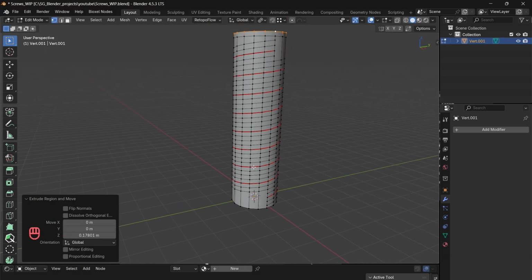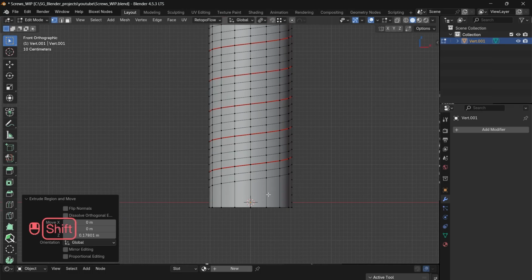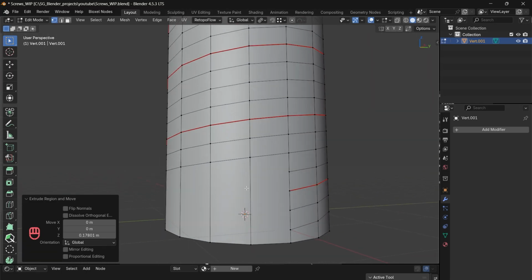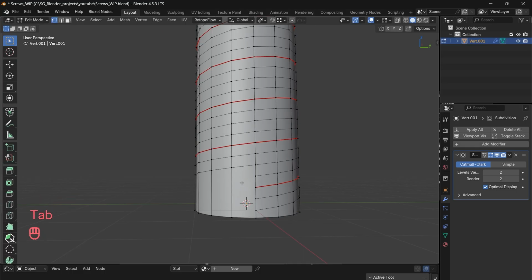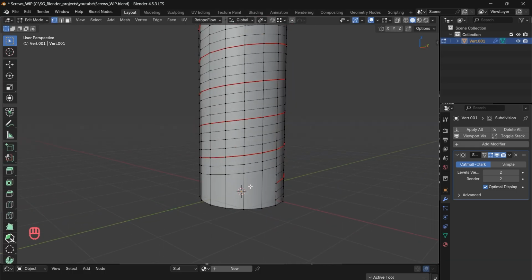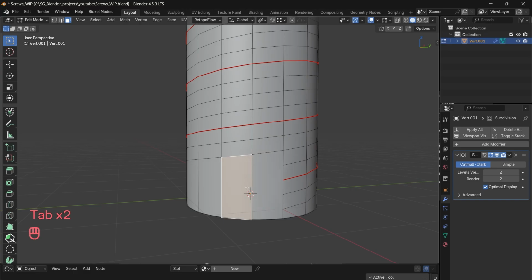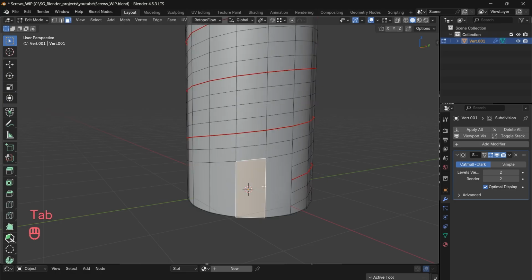As you can see here, the face size is pretty standard, then suddenly we're seeing very big faces. For this model, if I just apply a subD, maybe it will not cause much problem, but later if you try to deform it, it will. You also see that there is a big n-gon. N-gons are an absolute no-no, and there is some pinching effect happening due to the n-gon, so we need to correct that.